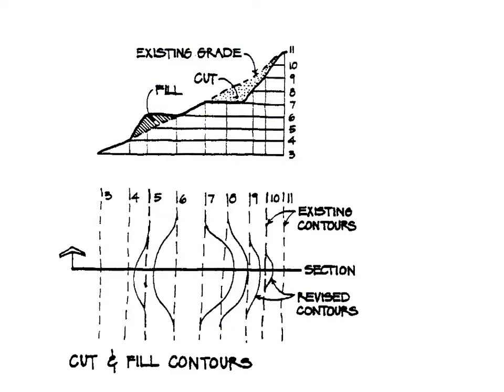What architects and designers and engineers do is we often modify the topography. And what we do are called cut and fill. Cut is where you cut into the existing slope and remove earth, and fill is where you pile dirt up. And so those are the two fundamental things. And one of the goals, actually, a lot of the time in site design is to balance them. It's hard to get rid of dirt you want to get off your site, and it's even harder sometimes to find dirt if you want to build things up. So having a balanced cut and fill, where you cut out dirt one place and move it somewhere else, is an important economic efficiency strategy.